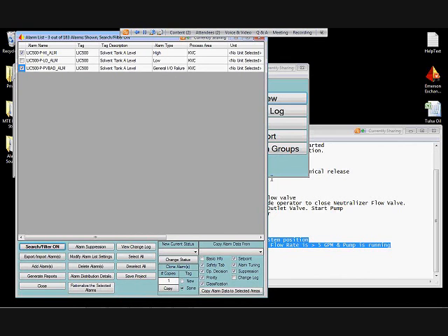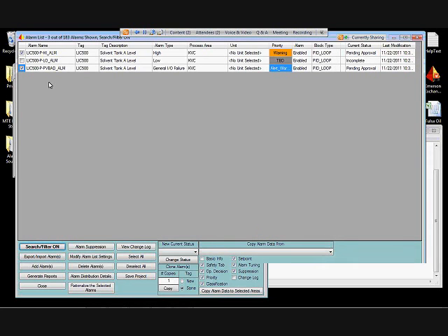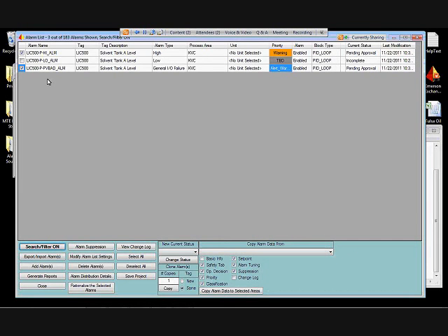And at this point, we would probably go through the MOC process to say, this is an alarm that was identified as a nuisance alarm. We've gone through the rationalization process. The priority is going to change. The limit's going to change. We've defined the operator actions. So the MOC team has reviewed it and approved it and authorized these changes.